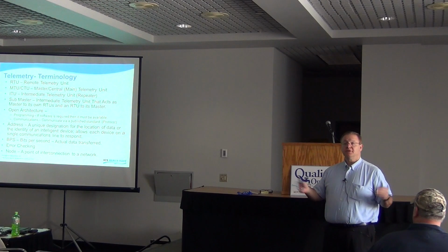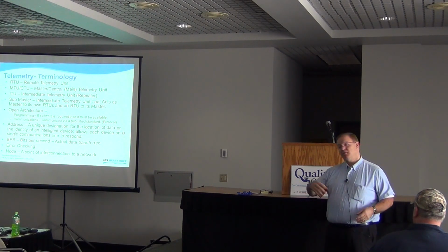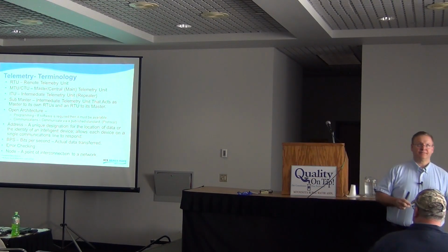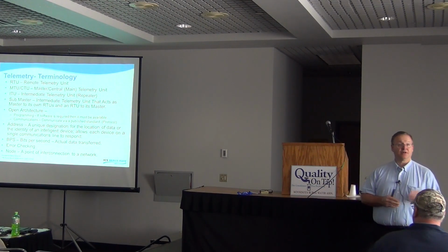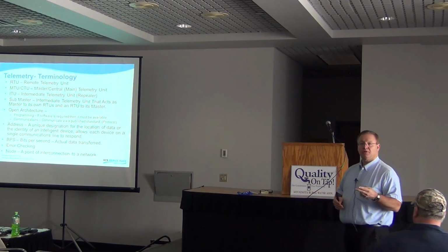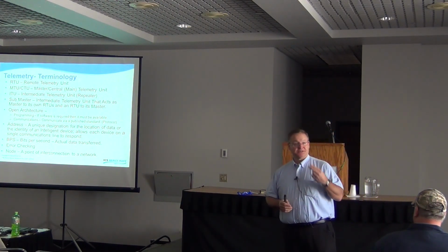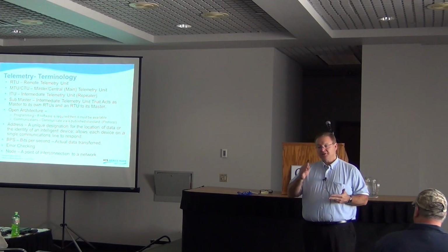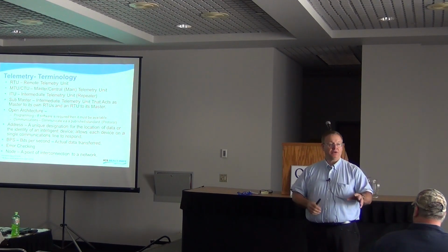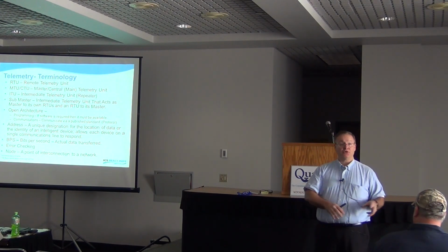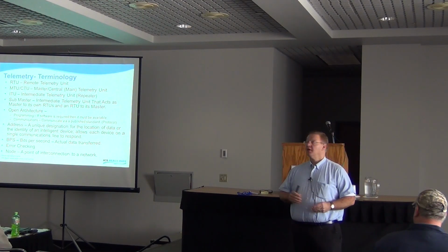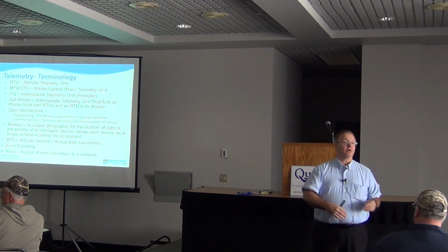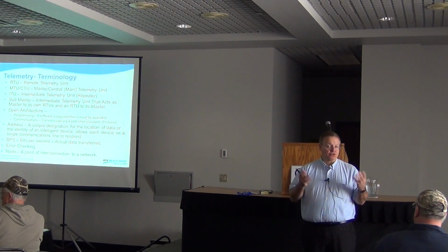Open architecture, often you're going to hear this in SCADA systems, well, we're open architecture. Well, there's a lot of differences as to what really is open architecture. In the SCADA world, open architecture exists on two planes. It exists in the programming world, and it exists in the communications world. When you're doing programming, what that means is that the software is available. You can buy it, or you can get it. You can program it yourself, or you can give it to somebody else and they can program it. It's not proprietary. It's not something you've got to run out there and buy a license for and maintain this kind of software. It's true open architecture.